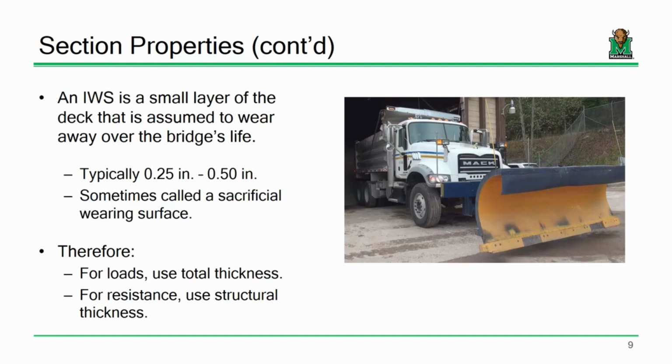And here's a common example, or a simple example to go off of. AASHTO has a standard vehicular model, a series of loads that they use to represent truck traffic in the United States, typical truck traffic. And that's the model that is the minimum standard across the country. But you go to Kentucky, and Kentucky says, that's great, we're going to use a model that's 25% larger, okay? And that's because in Kentucky they see larger loads, and that's what they need to use. So that specification makes sense for Kentucky.